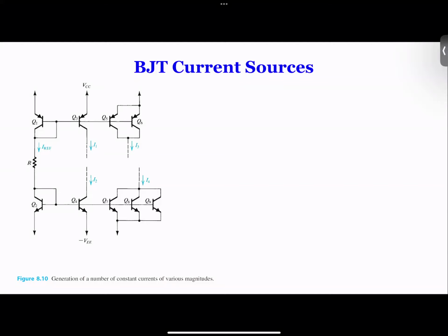So you're not going to have the same reference current anymore because there's too much current drawn into the bases. So for BJTs, we have to be careful how many we can connect from one. You just cannot do too many because there's base current. How do you calculate? Well, the area is designed in the process for building the BJT. It's given. When you build a BJT, you can build it small or big, so the area is given, right?